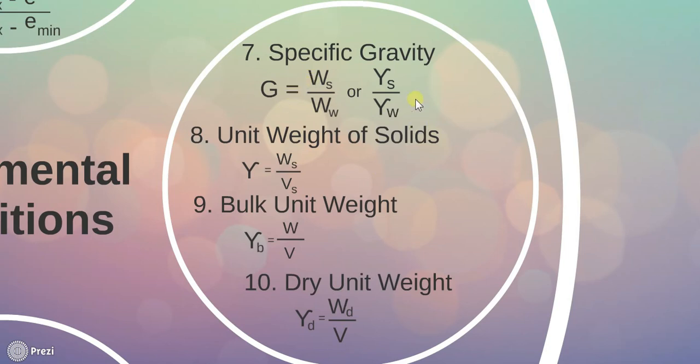Moreover, specific gravity is again divided into two parts, absolute specific gravity and mass specific gravity. Both have a little difference. Let us understand: if all internal voids of soil particles are excluded for determining the true volume of solids, the specific gravity obtained is called absolute specific gravity.